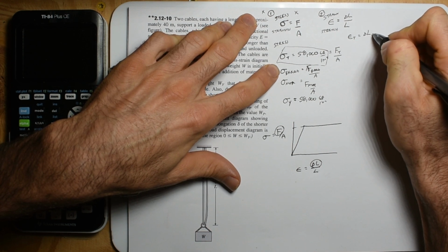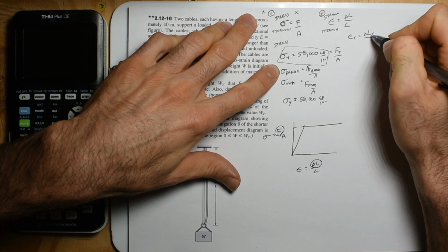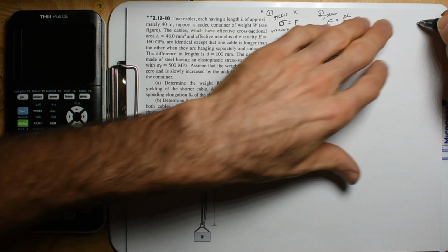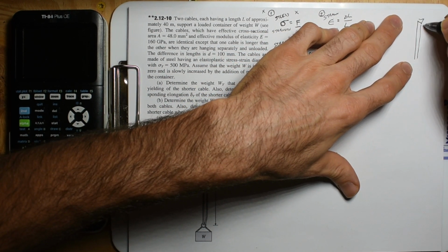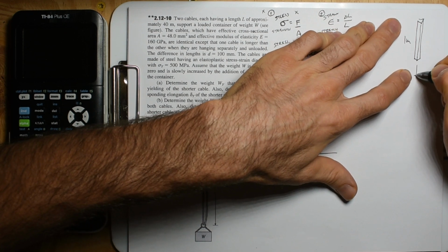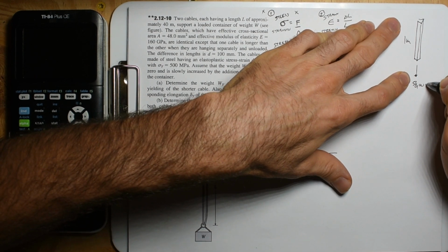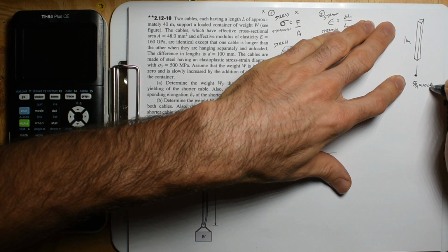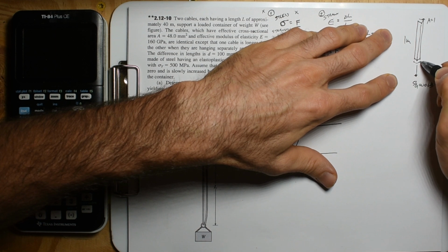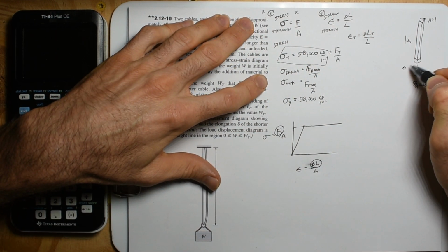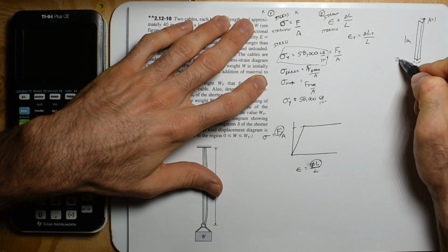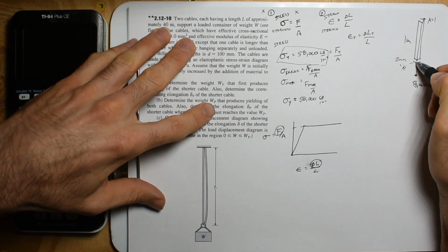You know what I mean? That's going to be your change in length due to that tensile strain divided by length. Now, what are we talking about? If we have a 1-inch steel bar that's 1 meter long, for steel we can put a load on it of 58,000, kind of the max load, 58,000 pounds over an area of 1 inch. And it's going to elongate. We can visually maybe see or measure that elongation. It's only going to be 2 millimeters, so that might be very difficult to see.